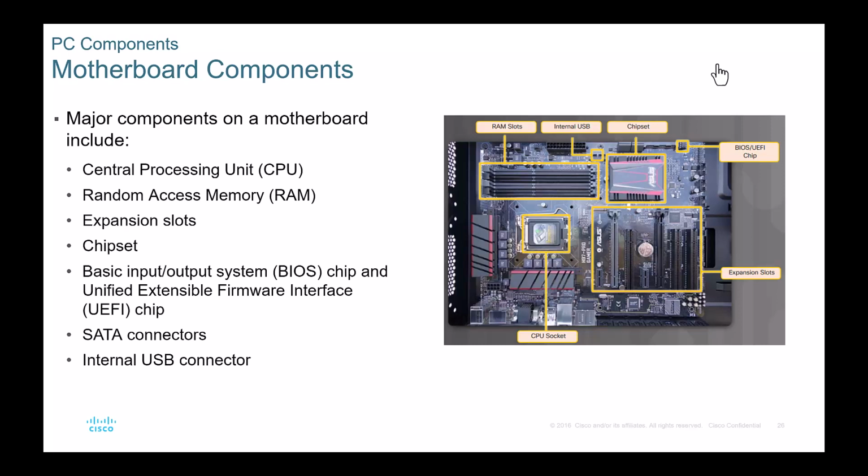So what's a telltale sign that you have a bad motherboard? What is one thing to look for when we're doing our physical inspection of it? I was going to say no POST. No POST, okay, but even just, hey, this isn't starting up, it's not posting, and you look at the motherboard, what is something that would be a telltale sign? Pins in the CPU socket. And pins in the CPU socket, absolutely. Anything else? Moisture damage. You can see moisture, maybe, yeah. You can see corrosion.